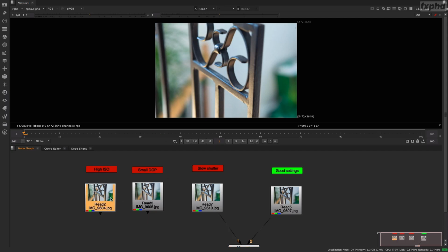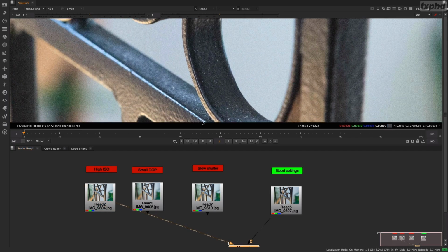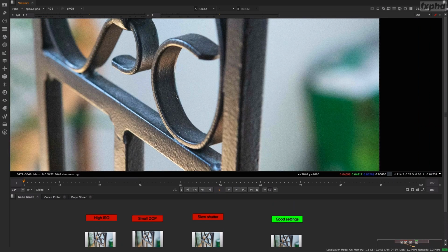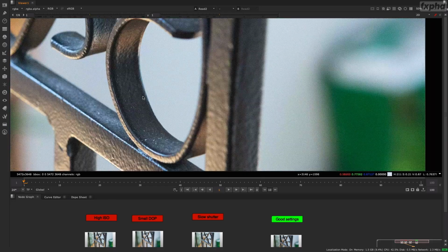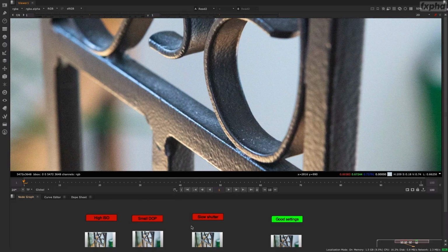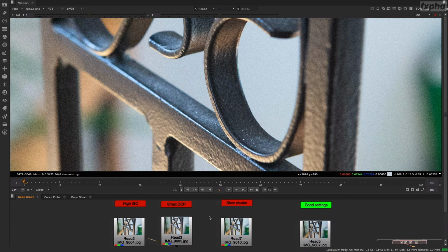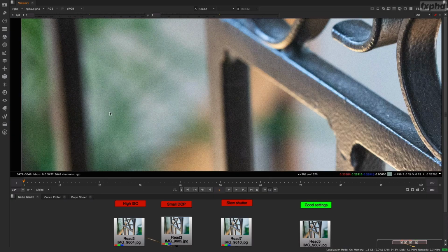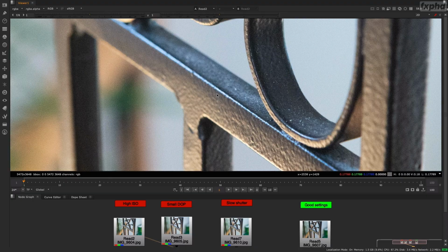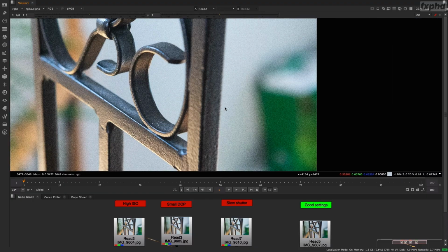The first one is the ISO setting. What you want to have, pretty much like when you're doing photo for anything, is an image with less grain if possible. The way this will affect the result of Metashape is that Metashape will solve a high ISO setting with a lot of grain as some bumpiness inside your object.